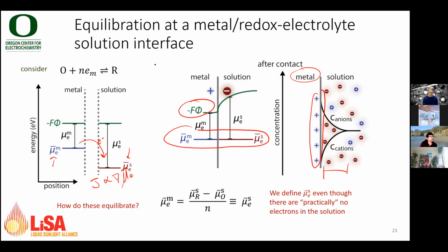If I take two metals, say titanium and gold, and I stick them together, titanium has very active electrons, a high Fermi level. Gold has stable electrons. They're going to transfer. And at that interface, you're going to have a buildup of charge. But a metal is very conductive. So the charges will accumulate at the very interface, as close as they can get to the interface, to lower the free energy of the system. Electrostatically, they'll be attracted to each other. And so this is the skin depth. We call it the skin depth of the metal. It's less than a nanometer. It's very, very narrow.